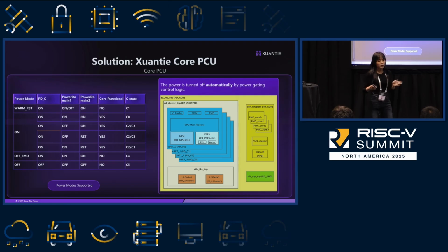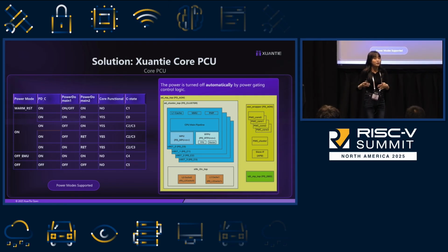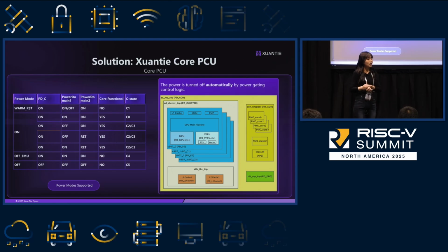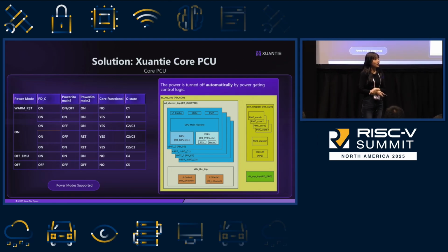If you want to go to the different types of power modes, you just set the different types of flags to the PCU, telling it what type of suspend I'm going to, and after you go to WFI, the hardware will do everything for you after that. So when you start WFI, you will keep on monitoring the wake-up event as well, right?